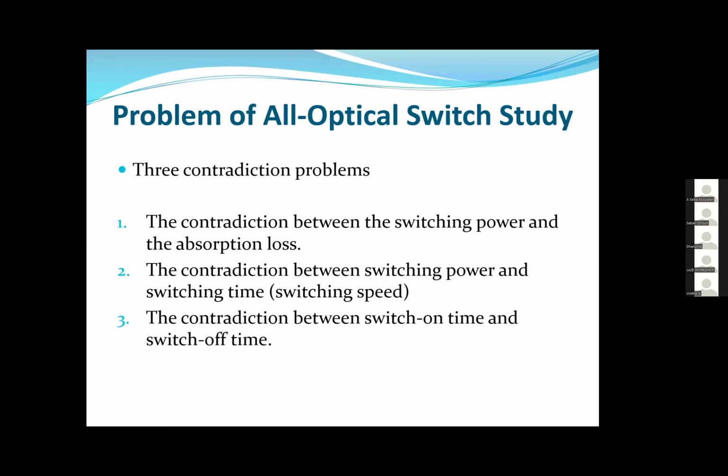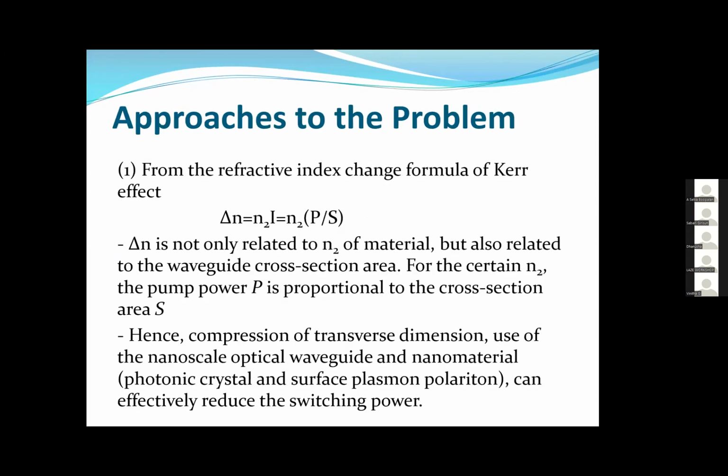Again, giving an example, a semiconductor all optical switch can achieve picosecond switch on, but the carrier recombination time needs dozens of nanoseconds. So for this, one may adopt ultra-thin interface or non-uniform medium methods to enhance the speed of carrier recombination. But the contradiction comes because this non-uniformity in the medium, though it enhances the speed of carrier recombination, may increase the optical absorption of the medium. So how am I to approach the problem?